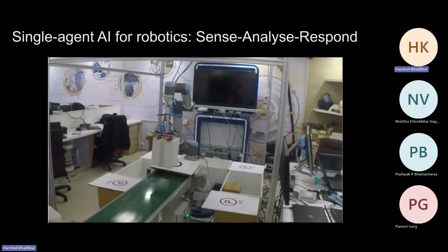Yes. So you have to know what is the grid. If you're looking at the bin top down, you have to know the height of each point in the bin, right? So think of the bin as a rectangle divided into a grid of certain dimension, say 1 centimeter cross 1 centimeter. If you know up to what height each cell in the grid is filled up, and you know the dimensions of the parcel that is coming up, you will know whether there is space for this parcel at all.